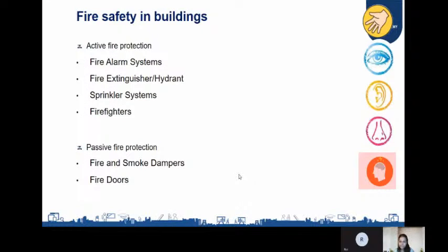So you can see here, if my heat strengthened glass breaks, it will break into a kind of island. Okay, it will create an island. If there is a crack in between, that crack will go till the edge. It will not stop in between. If my glass is in a four-sided supported frame, it will not fall out of the frame unless and until you deliberately go and push it. So you can have the buffer time to change the glass if it is broken.